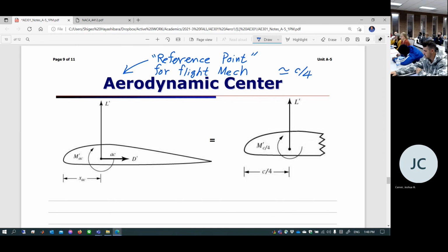What do you use the aerodynamic center for, in comparison to just knowing the center of pressure? In other words, you want to determine where the lift is acting. Lift is acting on the aerodynamic center, and that is going to create the control moments measured from the center of gravity. That's flight mechanics. So if the airplane lowers the elevator to pitch up, how much moment is generated is measured from the center of gravity to the aerodynamic center, because that's where the lift is acting through.